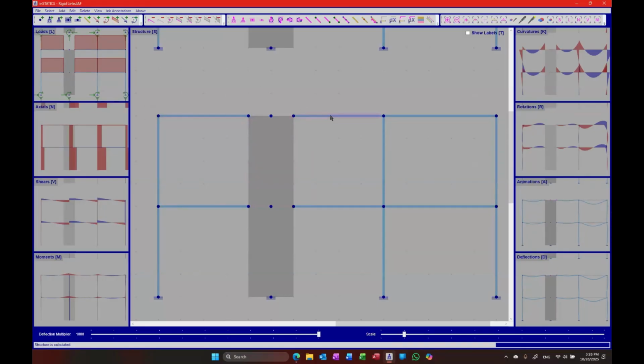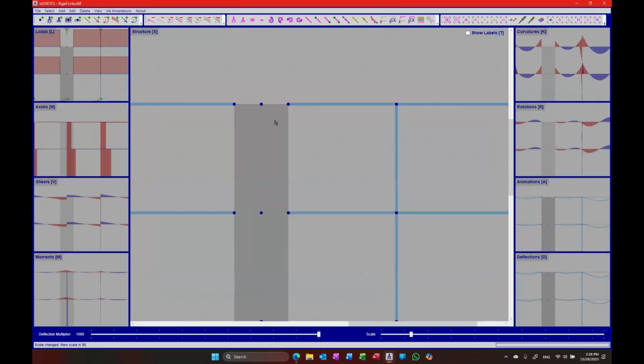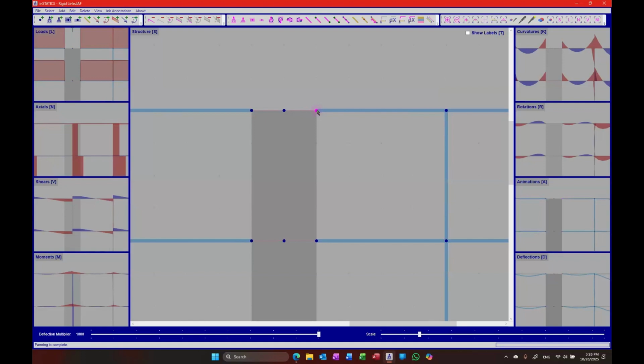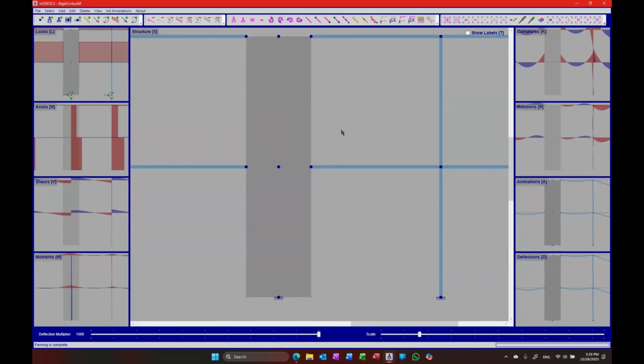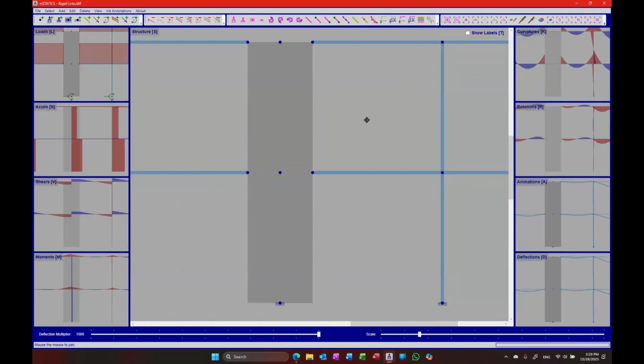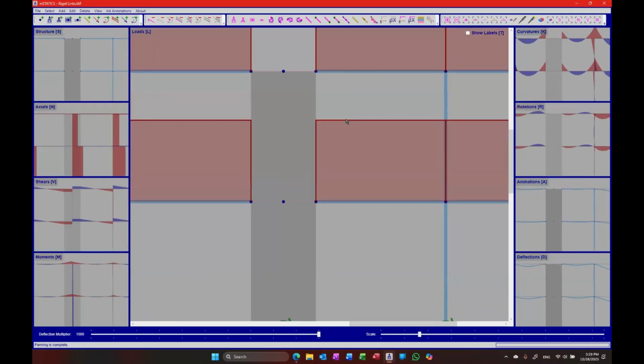Instead of one frame connecting from one node to the final node, there's an intermediate node where I connect, and then from the intermediate node to the center of this frame there is another element which I call a rigid link. And you can see them here as well. So those rigid links are very, very rigid, and we use them to simulate closer to real behavior.